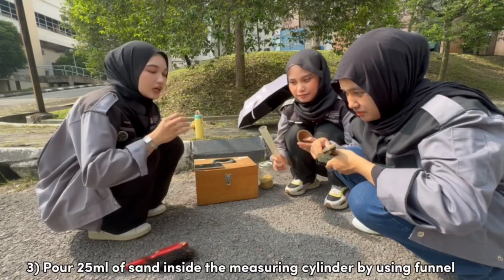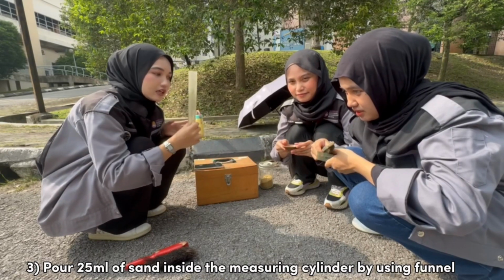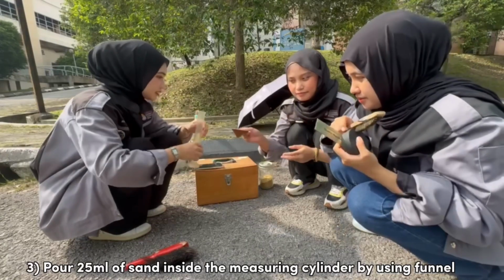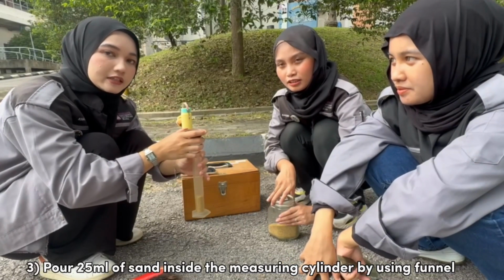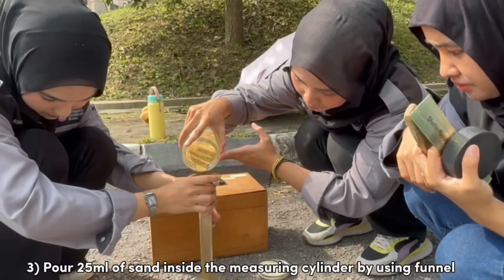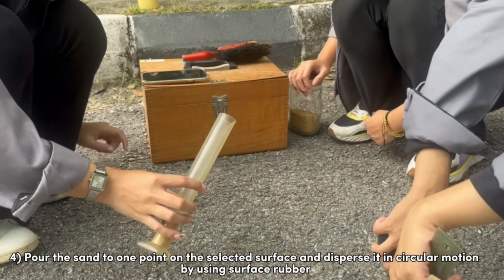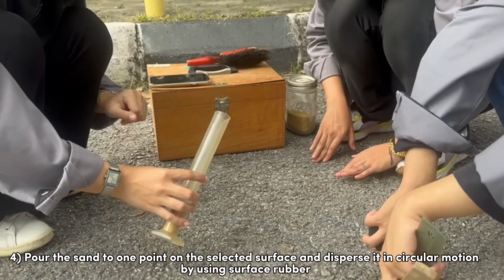And then pour 25 ml of sand inside the measuring cylinder. Pour the sand in the measuring cylinder by using a funnel. Then pour the sand onto one point on a surface road and disperse it by using a flat tool.